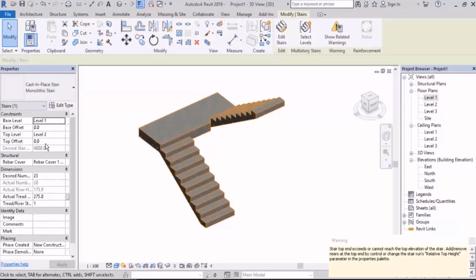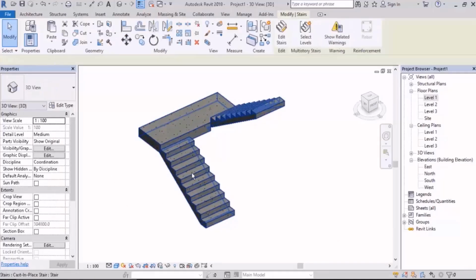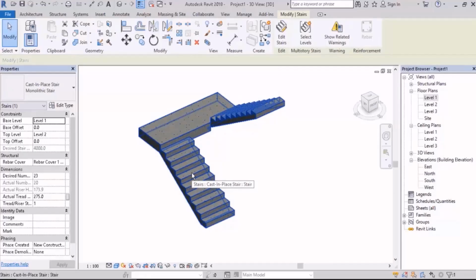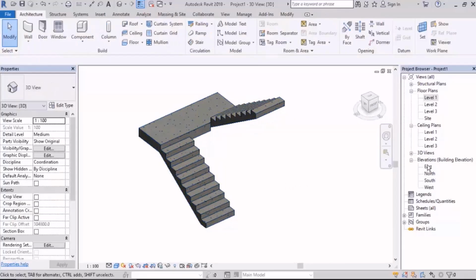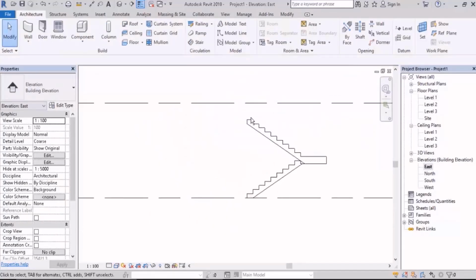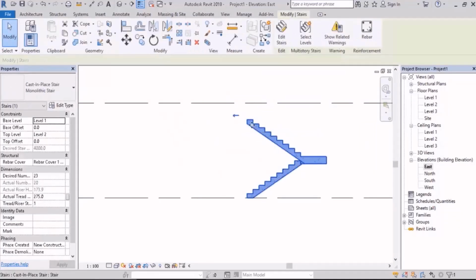The second step is about the technical settings. Let's have a section of it, and because it's repeated, you know it all. Alright, let's start. This is that crop, if you remember. I select the stair and then I go to the edit type. Naturally, we don't have support. It's actually not logical for the cast in place stair to have support because we have the structure beneath them, but you are allowed to have a support for it. I just don't tell you anymore. You can activate it and it will add support.